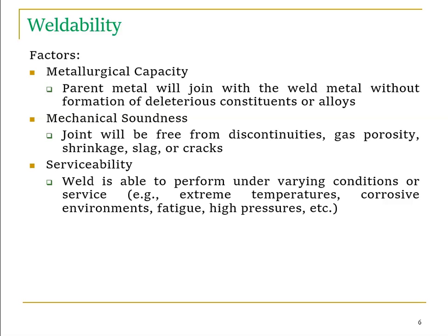Mechanical soundness means that after making the weld, the joint will be free from discontinuities, gas porosity, shrinkage, slag or cracks. So if you get a good weld, then we say it has mechanical soundness. The mechanical soundness should be higher if it is a good weldability.